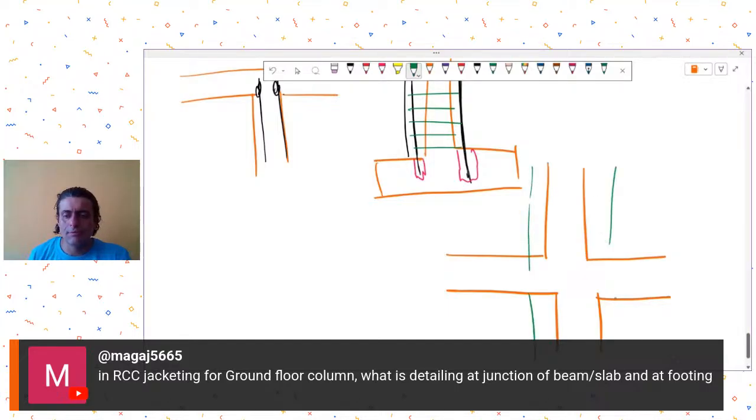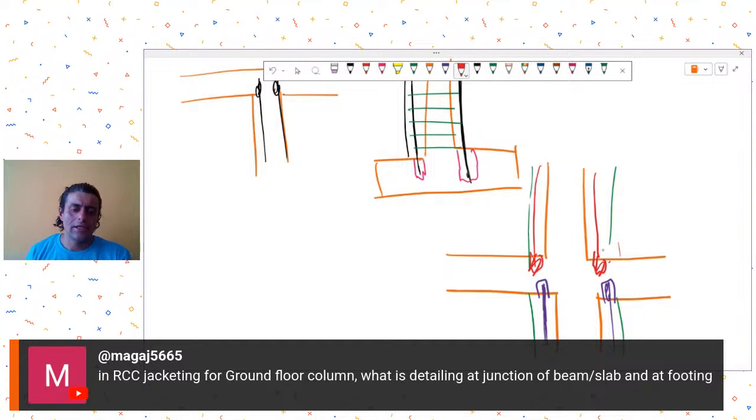So now this becomes slightly tricky. Maybe at the common reinforcement, you may not be able to do it through drilling. So maybe your bottom reinforcement stops like this after doing the drilling, and then you again plant a new reinforcement by doing drilling like this. Now it is possible that some of the reinforcements have to be passed through the slab.